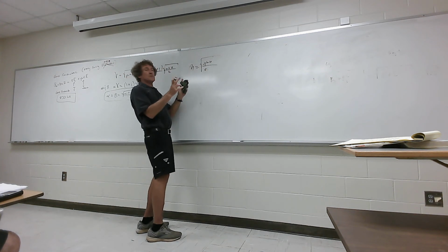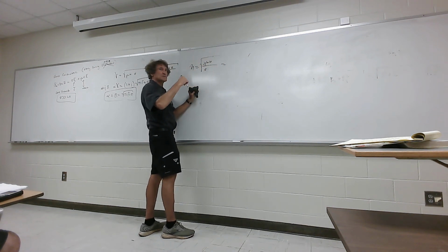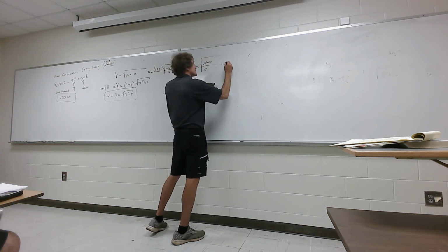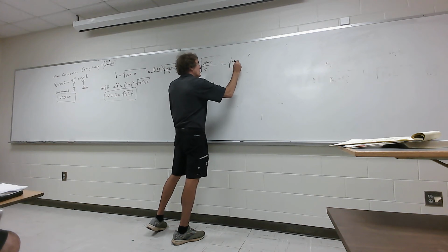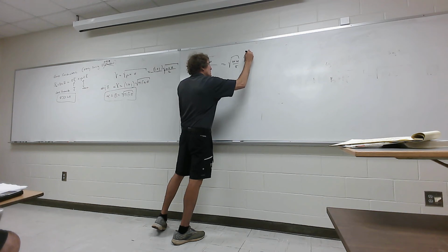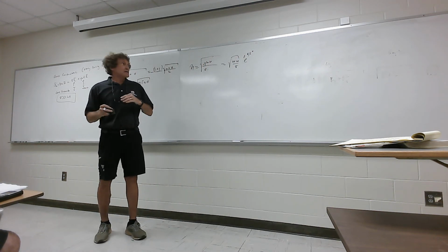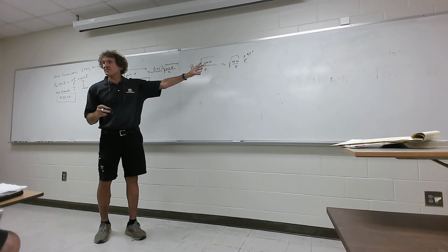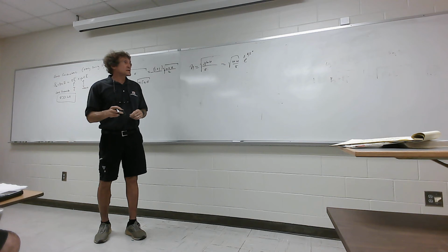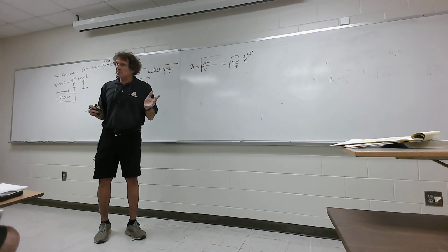Well, here you can write it a lot of ways. I'm not even going to blow up the J in terms of 1 plus J over square root of 2. I'm just going to say this is really square root of omega mu over sigma at an angle e to the J 45 degrees. Do y'all follow me? The only thing I've done there is I didn't bother making it real and imaginary. I'm just going to say it's omega mu over sigma at an angle of 45 degrees, which means it has a real and a complex part.